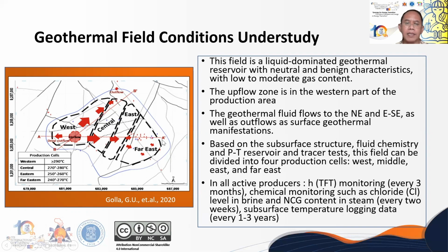In all active production wells, we conduct enthalpy monitoring every 3 months, chloride in brine, steam, and NCG in steam every 2 weeks, and subsurface temperature logging every 1 to 3 years.